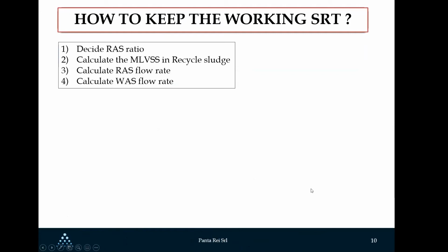So how to keep the working SRT? Please note that SRT is decided during the operation by the process engineer, and the SRT depends on the wasted sludge. Before calculating the waste activated sludge flow rate, we need to know the recycle ratio and the MLVSS in the recycled sludge. We also have to calculate the recycle flow rate and the wasted sludge flow rate.